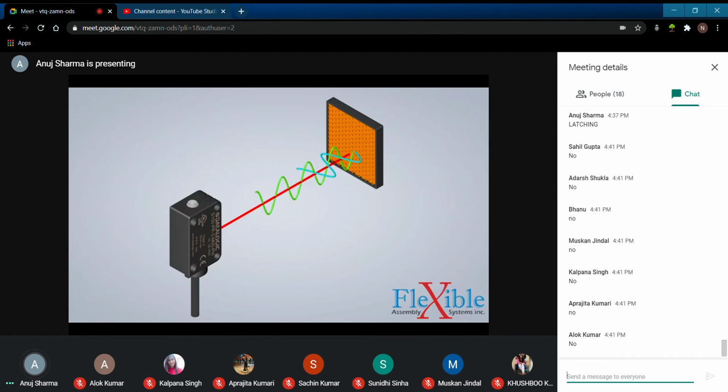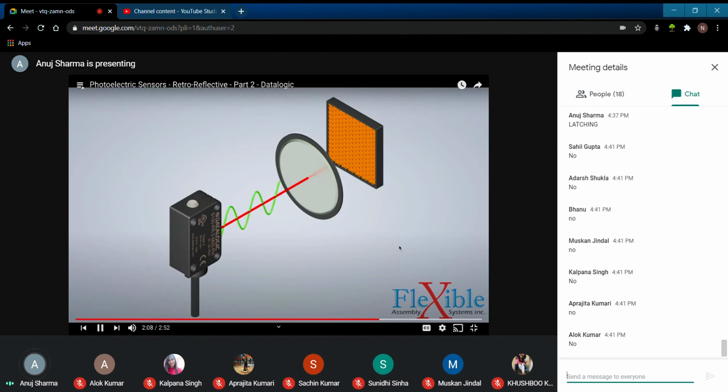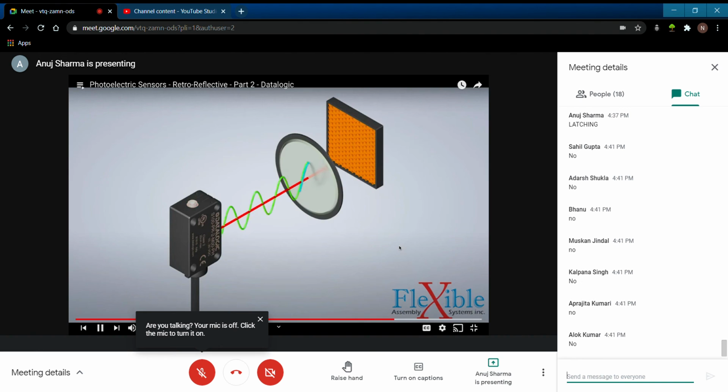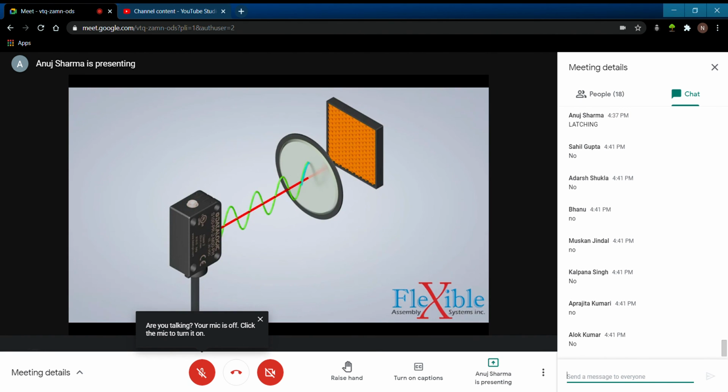When this happens, the sensor knows that no objects are present within its sensing area. So how do you tell when a shiny object enters the sensing area? When polarized light bounces off of a reflective surface that isn't a retroreflector, the orientation of the polarization doesn't change. A vertically polarized light would remain in that orientation as it made its way back to the receiver, and would be invisible to the receiver since it was only looking for horizontally polarized light. The only reflective object that could fool the sensor would be another retroreflector.